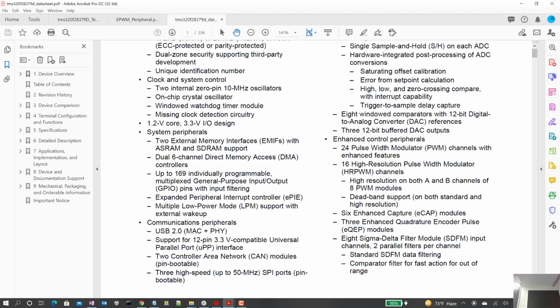And I start highlighting, okay, for this I/O pin, I'm going to use for the quadrature encoder. This I/O pin I'm going to use to turn on LED 6 or whatever. You have to kind of figure it all out and make sure you have enough I/O pins to do everything you want to. So what am I getting at there?